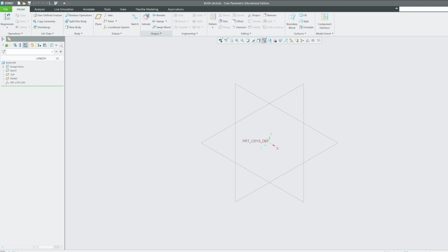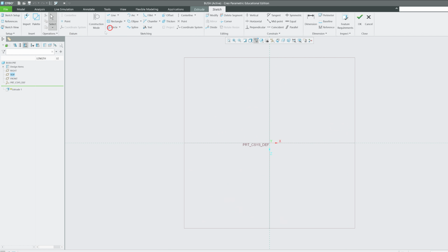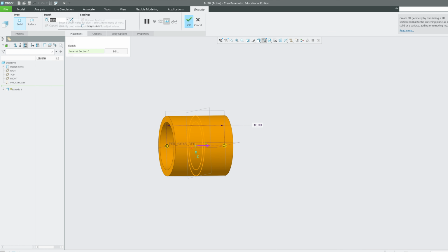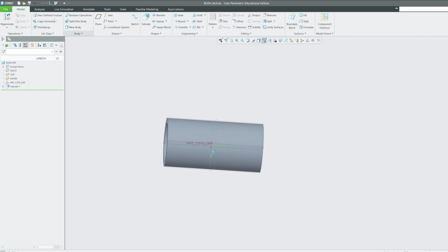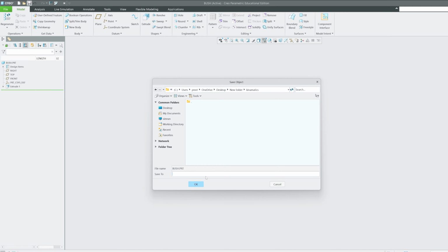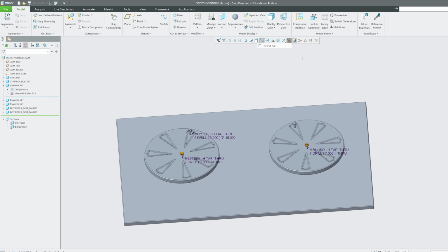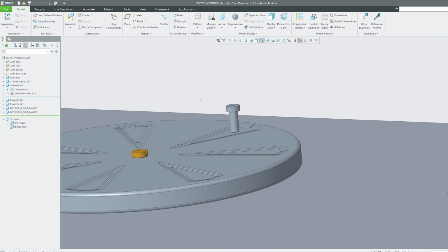And let's go here, extrude, circle, to circle. Inner one seems to need to be 8, and then outer one can be 10, or we will see, we always can change it. Now this needs to be 19.8. All right, so let's again save it, view, close, and now I'm gonna again disable all these.